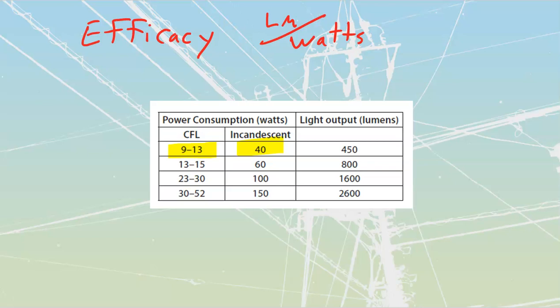CFLs, same thing. CFL stands for compact fluorescent, by the way, for those of you that have not seen that acronym before, compact fluorescent lamp. That's that section over there. But what we're seeing over here is that we're going to have about double the efficacy, sometimes double to about 4 times the efficacy, using the fluorescent compared to my incandescent.